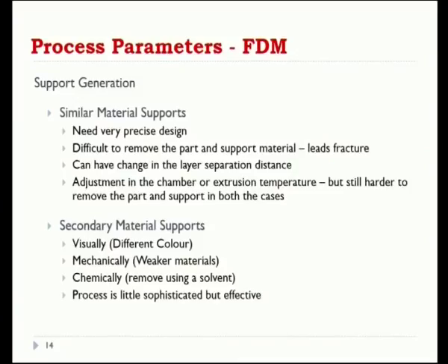One thing we can do is control the chamber and extruder temperature. If you alter the extruder temperature, what will happen? Exactly, the flow rate can be modified. Based on that, the problem is that removing the part is a little harder in both cases, because there is different temperature, different cooling rate, different drying effects, and the part which is laid on the top has different drying effects. So this may again lead to problems in separating the major components.